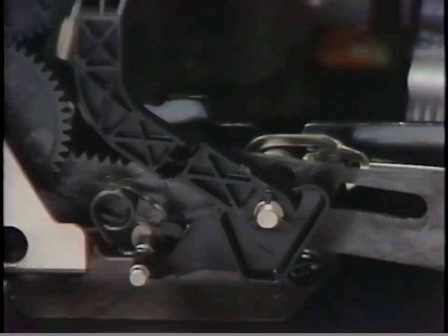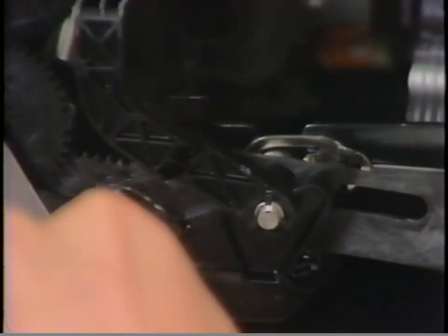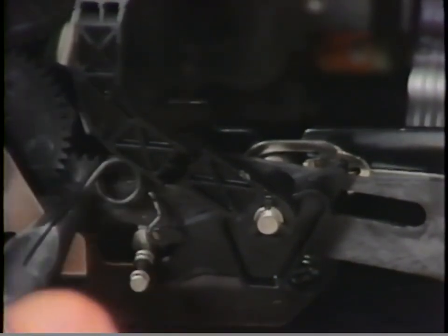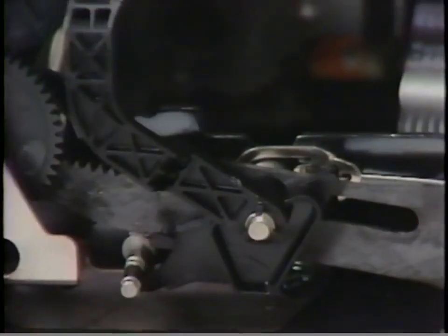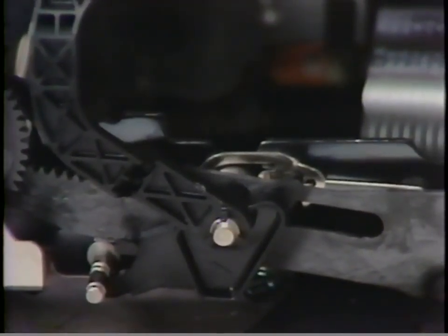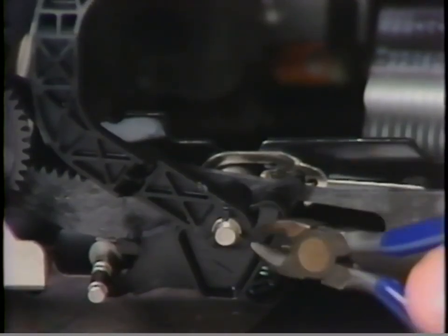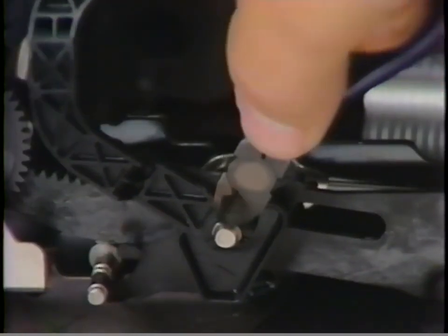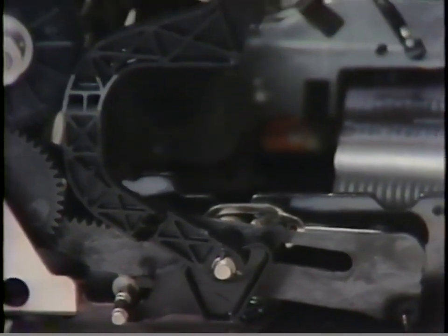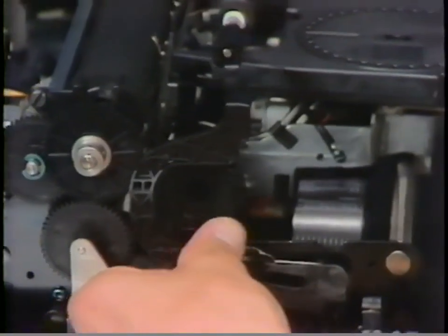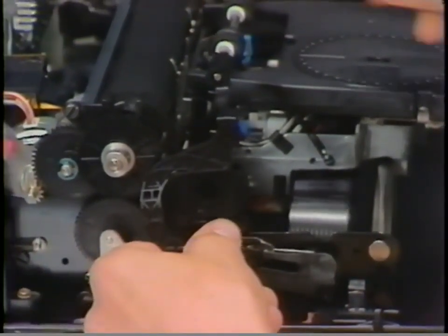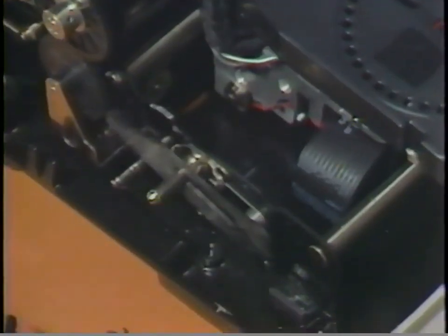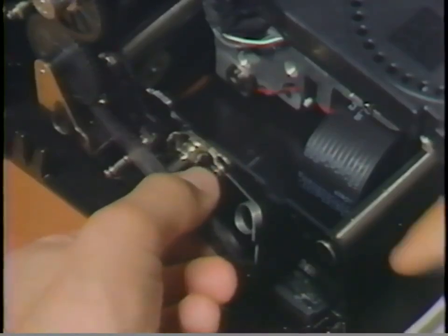To remove the first writing line knockoff, first disconnect the paper bail arm toggle spring. Clip the holding tabs on the paper bail arm. Then remove the paper bail arm. Anytime you remove either paper bail arm, you will have to replace it with a new one. Remove the first writing line knockoff.